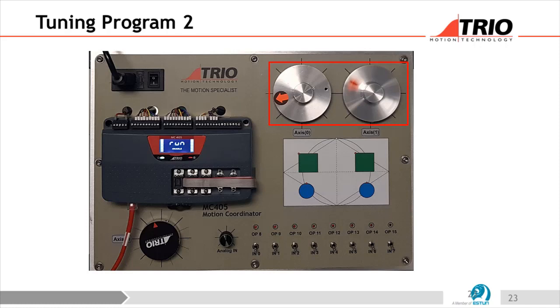So before you do anything else, set the D gain to 30, otherwise they'll go unstable because there's no speed loop in the drive. So the D gain here, this differential gain, is acting a bit like a speed control. And it's because these drives have no speed control, they're just torque. And that's the only additional thing.